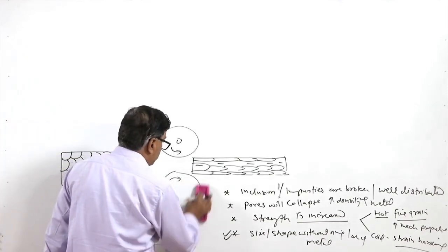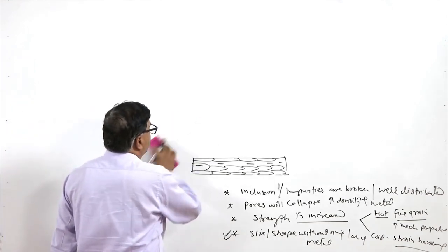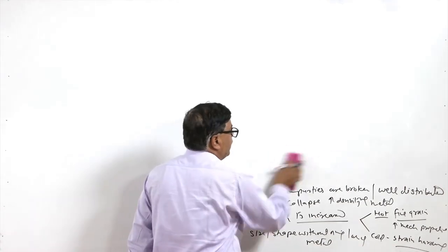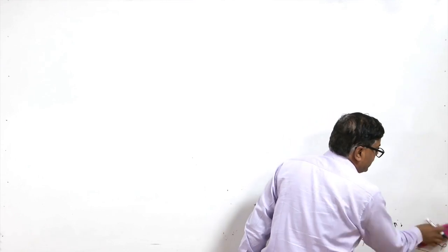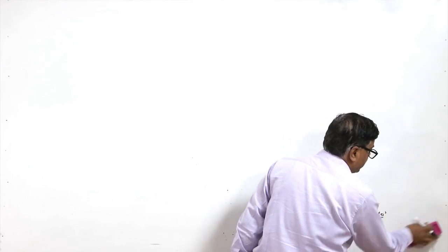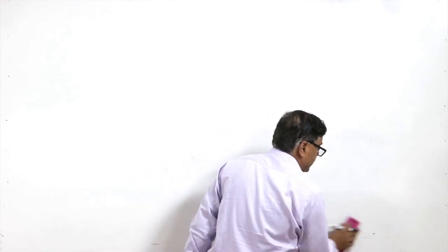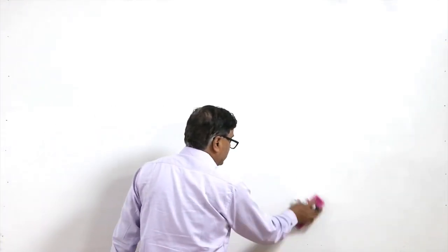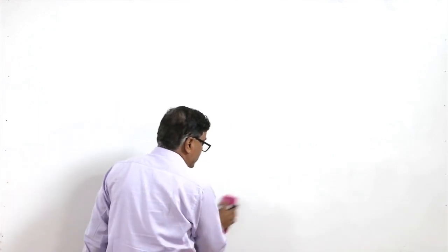removed. So, in order to facilitate the plastic deformation in metal working based processes, normally the heating of the metal is carried out so that the deformation can be achieved easily. We know that at the room temperature yield strength of the metal is high and the ductility is low.